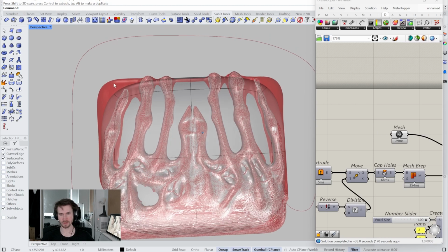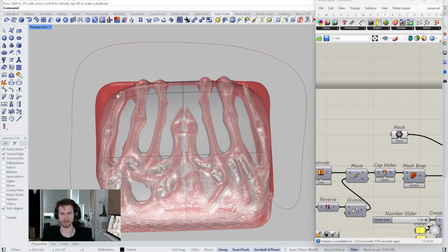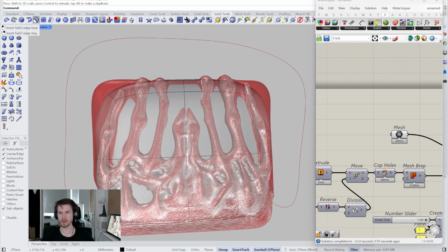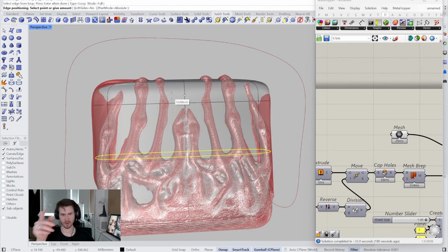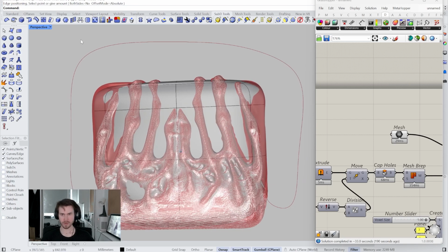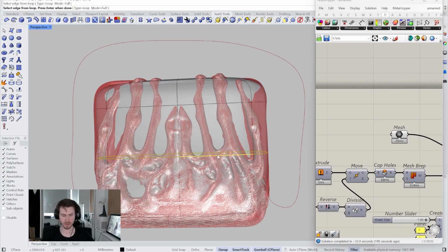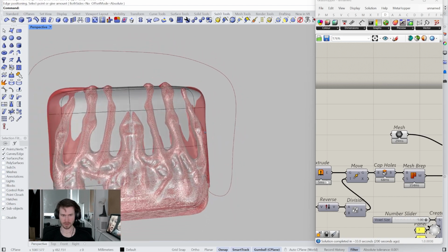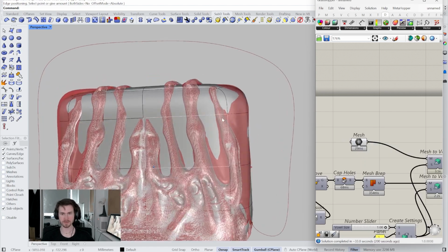And then just finally, to get these nice corners, we'll add some edge loops in here to just round off all the corners a little bit better. So let's insert a sub D edge loop and go here, move that up, and then you can see we're getting that curve a lot better. We'll just probably go about there. We'll do this for the bottom as well because we can see it's starting to neck in right there. Do it again, I'll just pull one down. That looks a little bit better for what we had. Again, remember the rest of this is covered by the actual pattern, so we don't have to worry about the bottom too much.